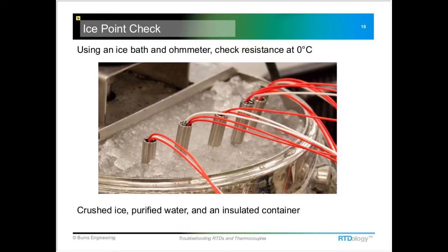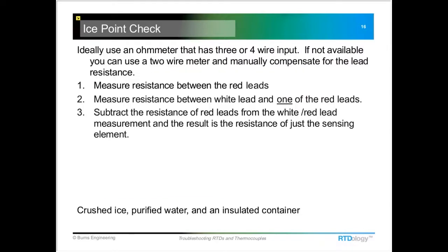One thing you have to be cautious of is you don't want to use the probe to jam a hole into the ice. You'd want to use a screwdriver or something other than one of your good probes to pound a hole in that ice, because that can damage the probe even further. So make sure you make those holes with something other than the temperature probe. You want to put it in that ice bath and let it stabilize for a few minutes. Hook up the ohm meter and see what that measurement is.